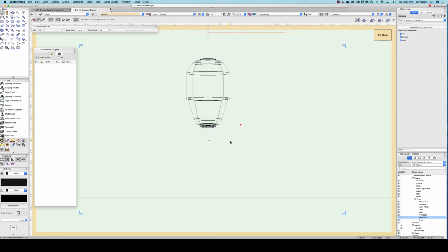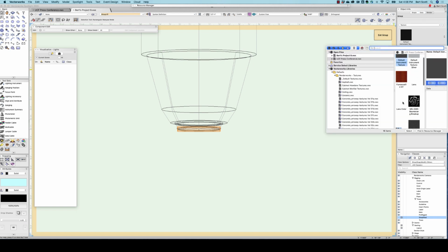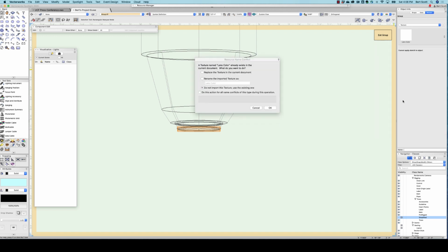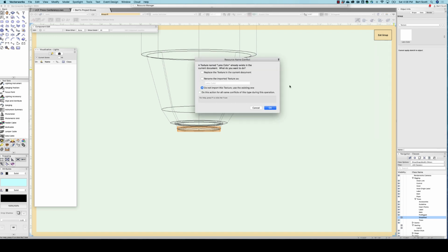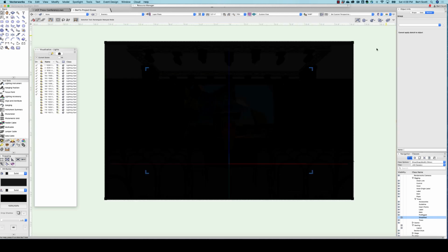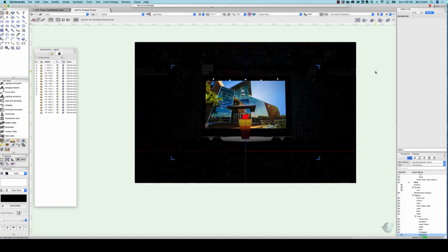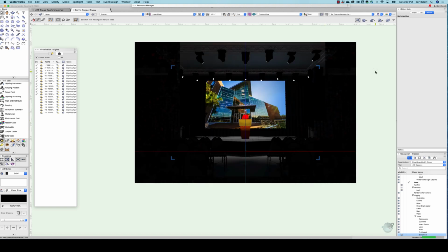Double click here, select this piece, which is the lens, and change the render from default instrument texture to lens color, which should be in your document. You may not get this dialog, but if you do, just use replace. Now you'll see that the lenses are now on.